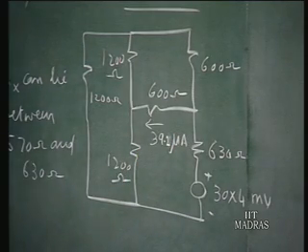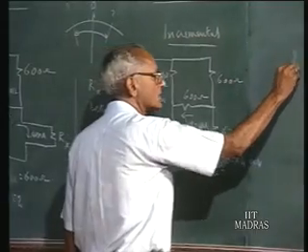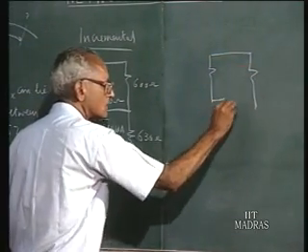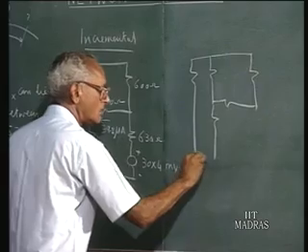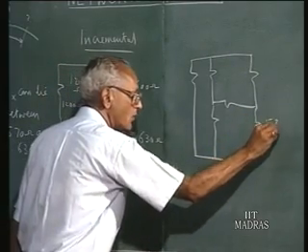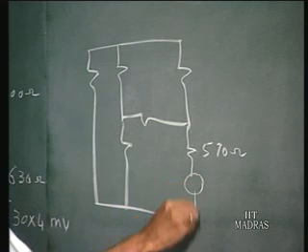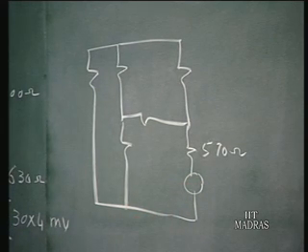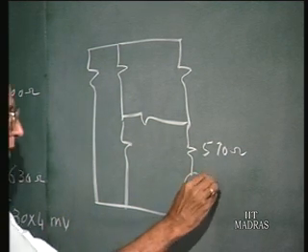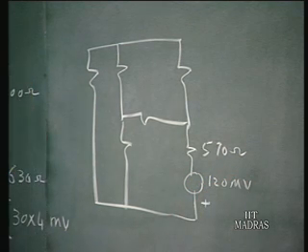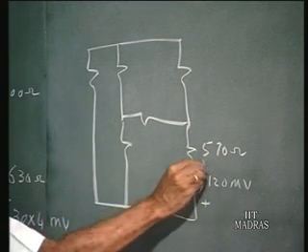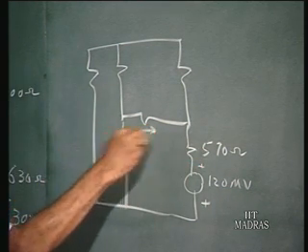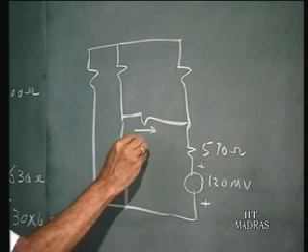In a similar fashion, you also calculate the current in the galvanometer when the resistance changes to 570 ohms, and now the change in the resistance is minus 30 ohms, and the original current is 4 milliamperes. That means the voltage will be 120 millivolts in this direction, because delta Z is negative, therefore it should be in the opposite direction. So with this you can calculate the current, and this can be shown to be equal to 40.8 microamperes.